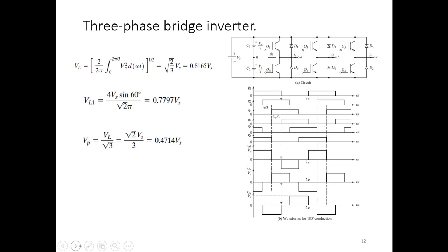Then you can also have a three-phase output. This is your gate signal, the three gate signals 1, 2, 3. Each one is 120 degrees phase shifted, and 60 degrees between the six. This is the first one, and the second one, the third, the fourth, the fifth. You generate a pattern of logic signals with 180 degrees on, 180 degrees off, and then shift by 60 degrees because there are 6 of them in total, and that's what generates those signals.